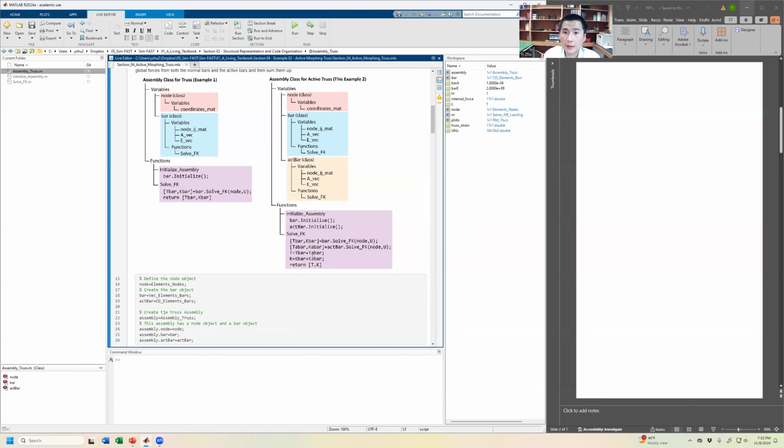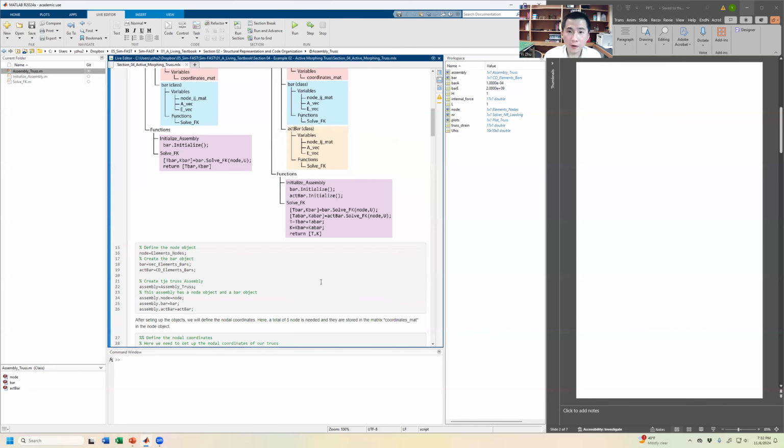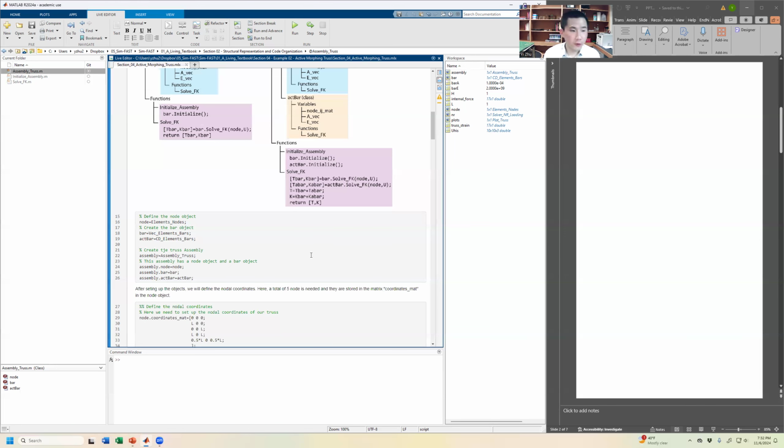Later in the next 3 sections, I will be talking about how the bar elements are formulated, how to achieve the stiffness matrix and global force vector assembly, and then also talk a little bit more about the Newton-Raphson solver for nonlinear problem. It's an implicit solver. That's the theory part, but without going too deep, let's just focus on this example to see what we can achieve once we have those theory ready and organized in a code package.